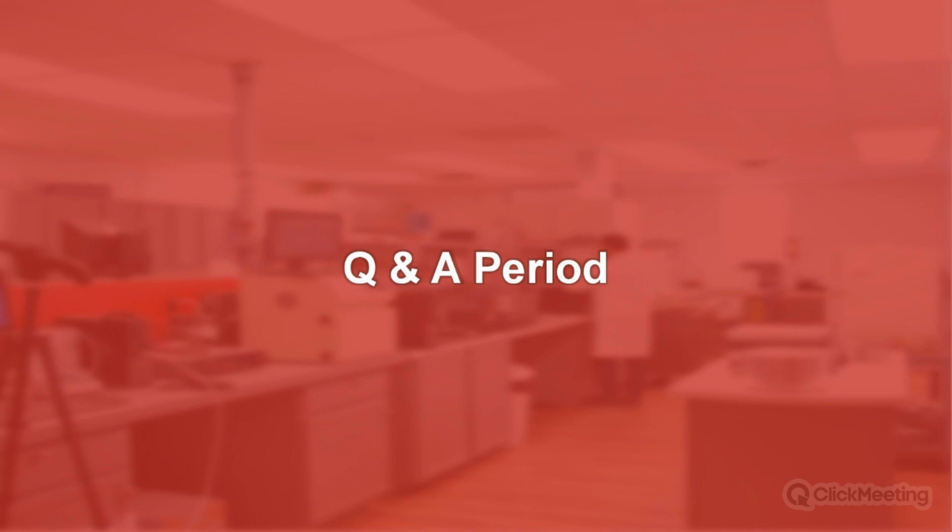So it's a difficult task. Of course, there are other methods that are not discussed here, such as transient line source. That has the same considerations as the TPS method, that you want to make sure you're using a sensor with enough volume penetration and that you're removing the nonlinear portion of the data, which still is going to have some effects of other modes of heat transfer in it.